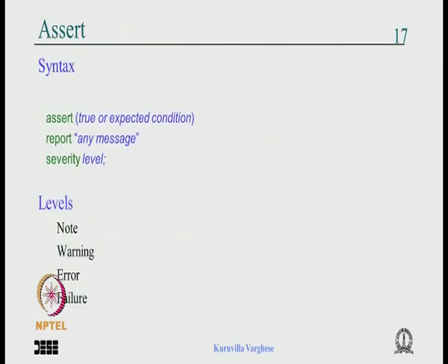So I think that is where we take a brief look at delay modeling. As I said, there are 2 delay models. One is inertial delay, which is used for the gates, which has 2 parameters: minimum pulse width for the output to come, and a propagation delay. In the simplest case, the propagation delay and the minimum pulse width are assumed to be the same, which is somewhat near real life, but they need not be exactly the same, and you can specify a different pulse width.